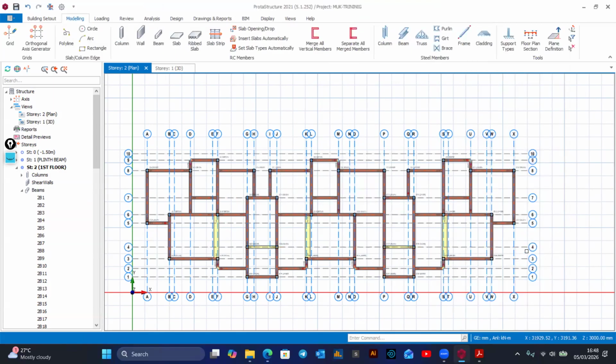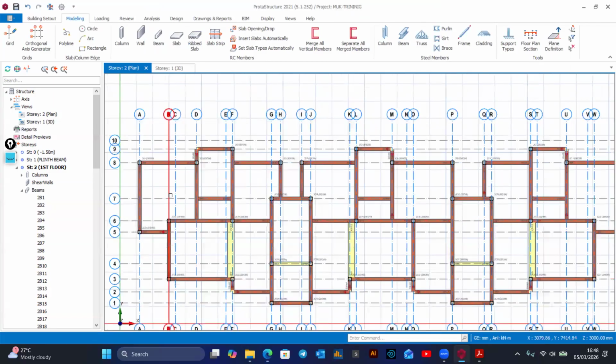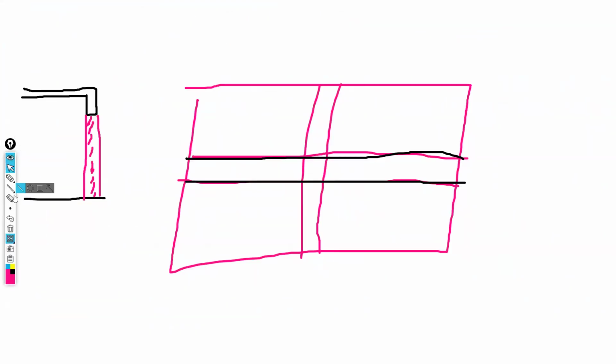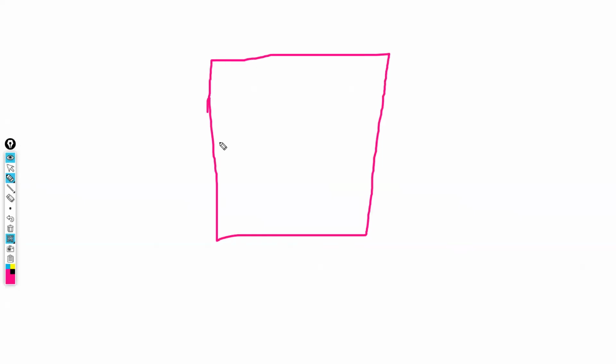Yes. We're adding this beam to have a transition between a hollow slab and a solid slab. Because what's going to happen on site? I'm assuming that if these are my panels, the beam is here, right? This part is solid, this part is hollow.